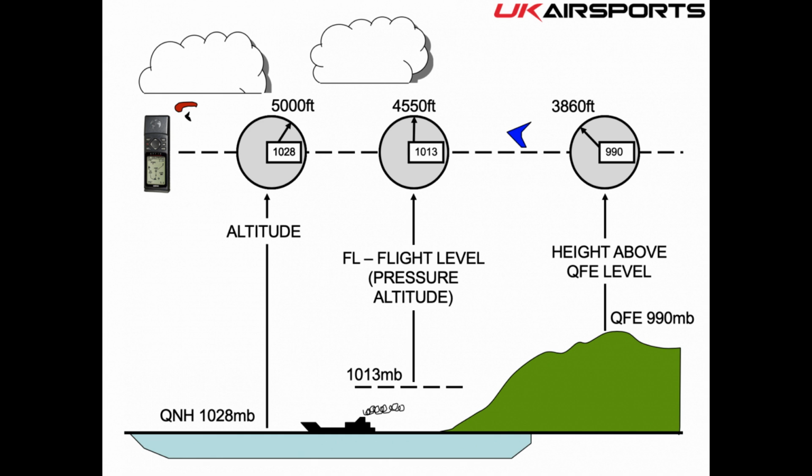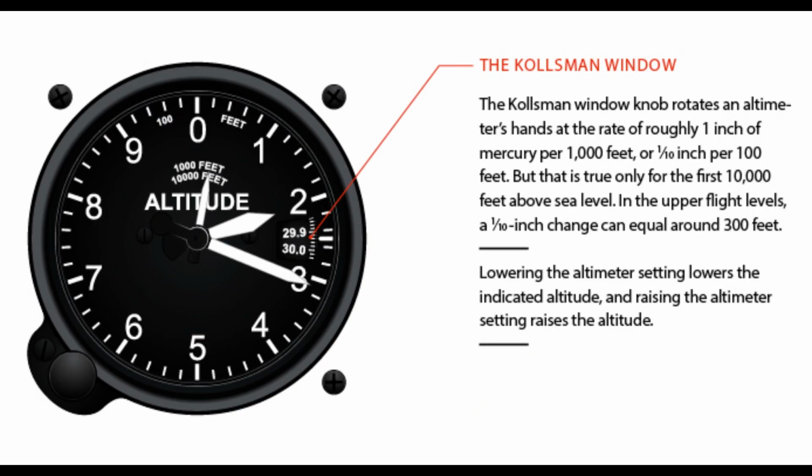When the minimum altitude, as prescribed in 14 CFR Part 91, Sections 91.159 and 91.177, is above 18,000 feet MSL, the lowest usable flight level is the flight level equivalent of the minimum altitude plus the number of feet specified according to the lowest flight level correction factor as follows.